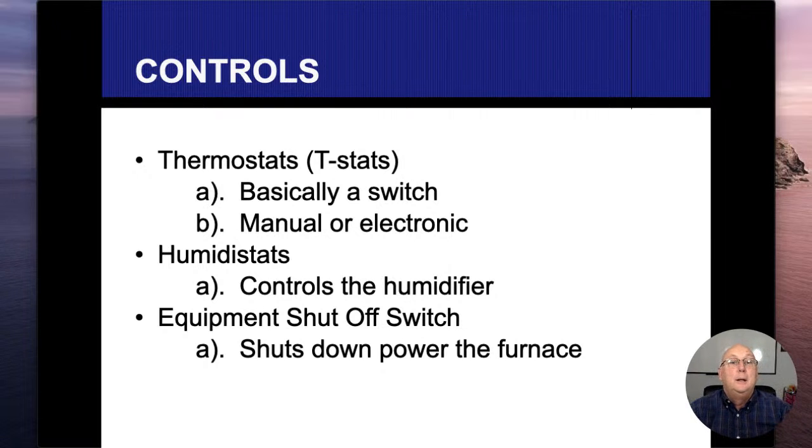All right. Humidistats are basically the same thing, only they use humidity sensors to turn the humidifier on and off. So that's also a switch. The isolation or equipment cutoff switch, we should find within reach of the furnace, so somebody can work on the furnace and turn the power off to it without taking a chance that the thermostat automatically turns the furnace on.